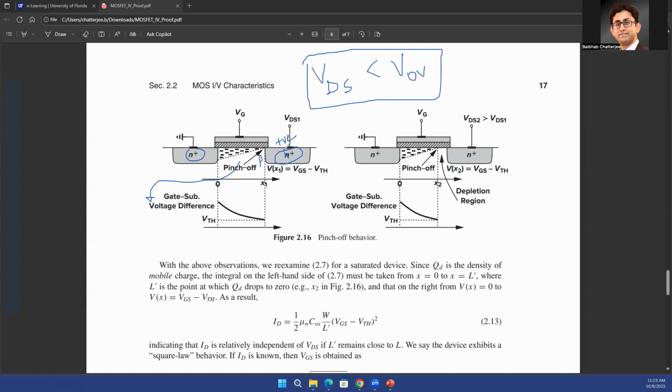If you reverse bias a diode, the depletion region, that is the region where you do not have any majority carriers, keeps on increasing. This is the same thing that is happening here: as you apply a positive voltage at the N-type drain region, your depletion region widens, which means the number of majority carriers near that PN junction decreases, so that depletion region keeps on getting wider and wider.